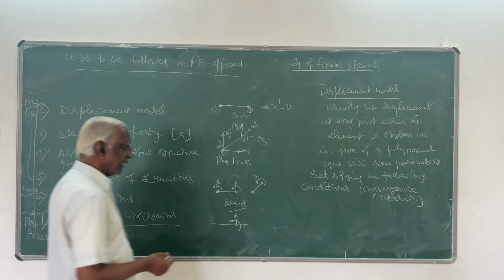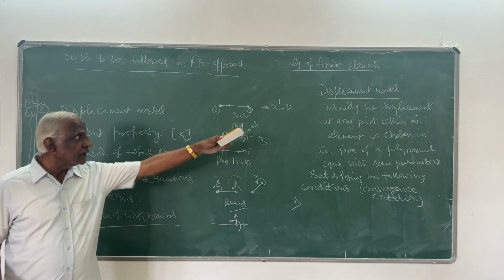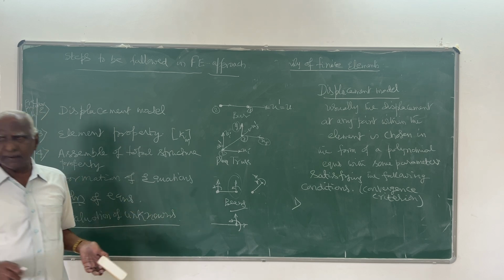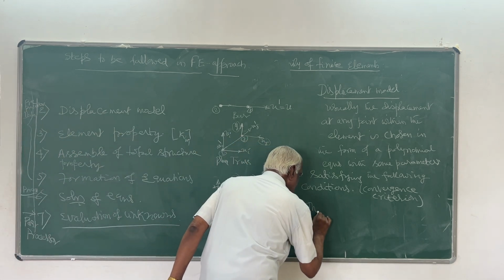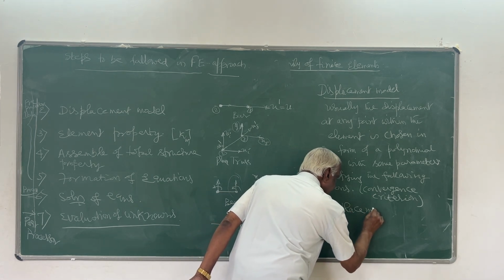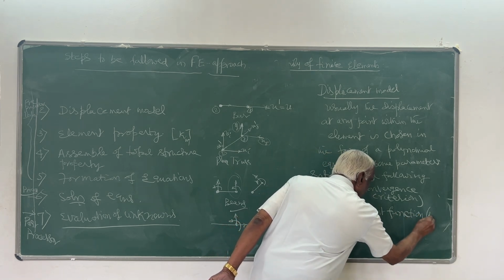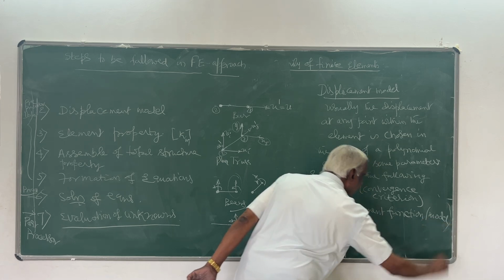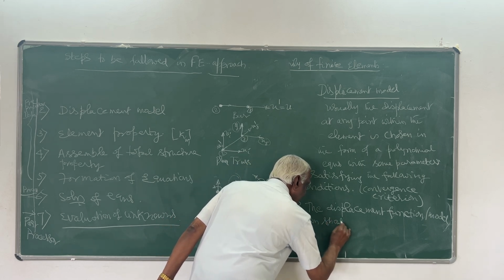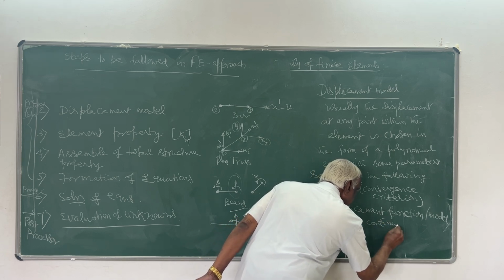So the first convergence criterion is that the displacement model or equation which you choose should be continuous and complete. The displacement function or model chosen should be continuous and complete.